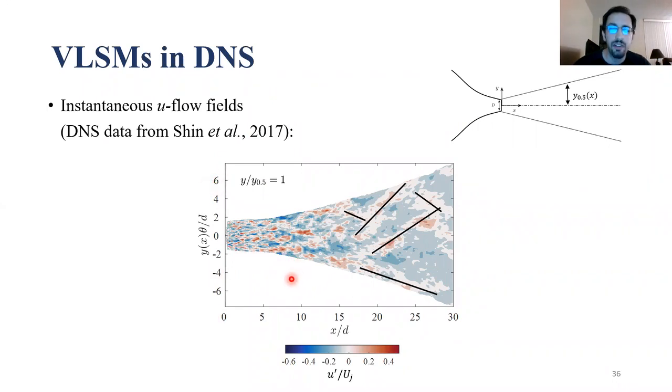And the reason why we have an unwrapped cone rather than an unwrapped cylinder, for example, if we were looking at the flow in a pipe, we would normally have an unwrapped cylinder because the radius of the pipe is a constant. But in a jet flow, because the jet half width grows with x, and we want to be able to follow the structures that grow with the jet, we look at a cone and unwrap it, so the result looks like a triangle. So I just wanted to explain to make sure that everyone understands this flow field.